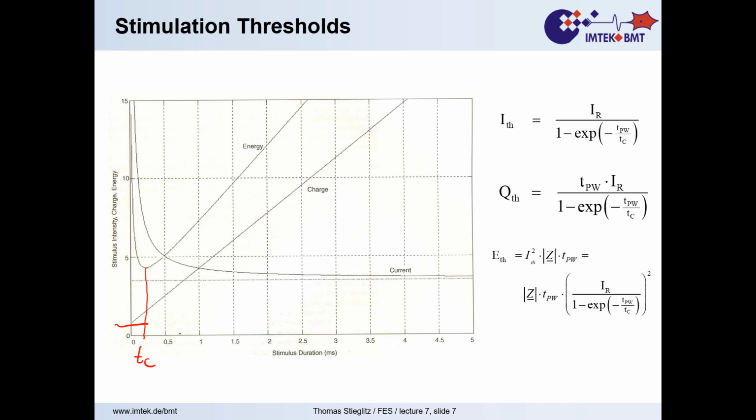And depending on the application, on the site in the body, on the species that you use, that chronaxie varies a bit, but is roughly in between 70 and 150 microseconds. So our pulses are relatively short, which is good for electrochemistry if you stimulate only 150 microseconds. So there is nothing, let's say, that is long-term there. So, and then if you have that charge balance, you can probably minimize the side effects on electrode corrosion if you do it in a clever manner.